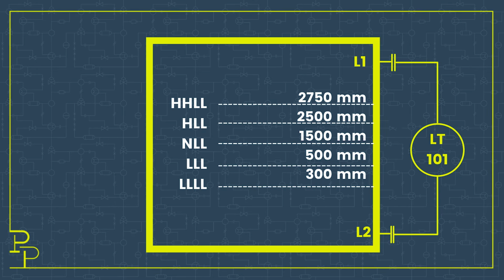What we call high and low depends on the specific design of the plant and the considerations around why we would want to stop the plant or trip something. But one thing I forgot to do is to show that often on P&IDs, we show what these levels actually are in height terms. So we put them in millimeters or inches. And what you see here is the middlemost value is the normal liquid level, NLL.